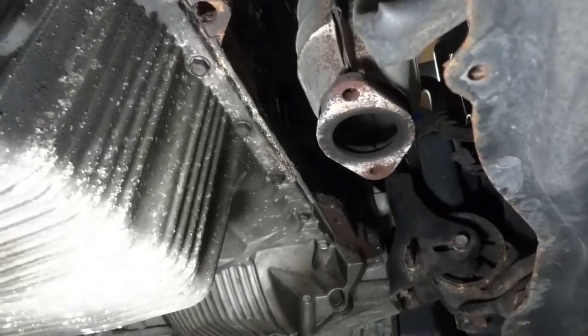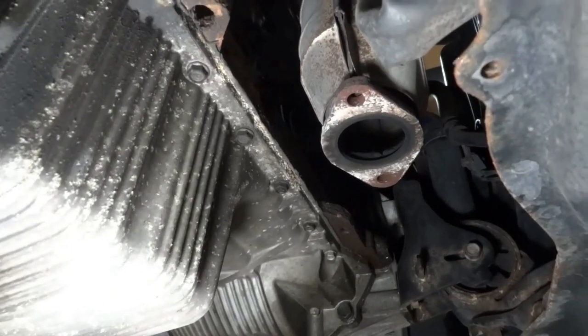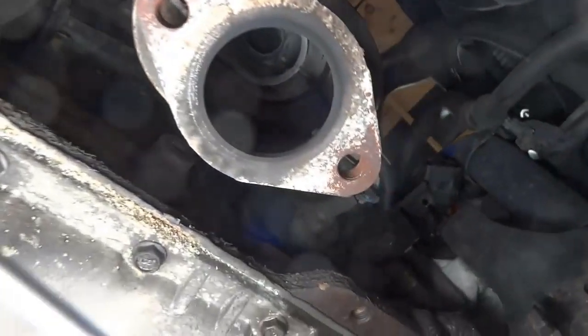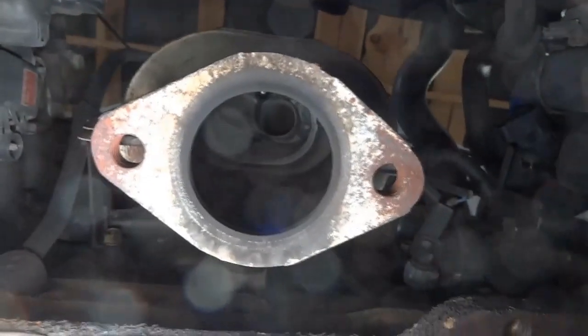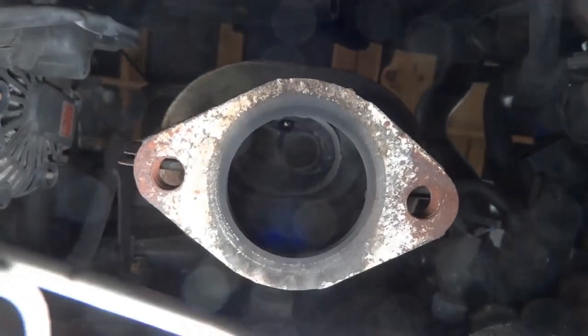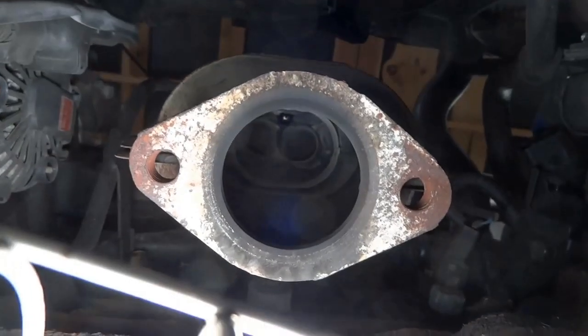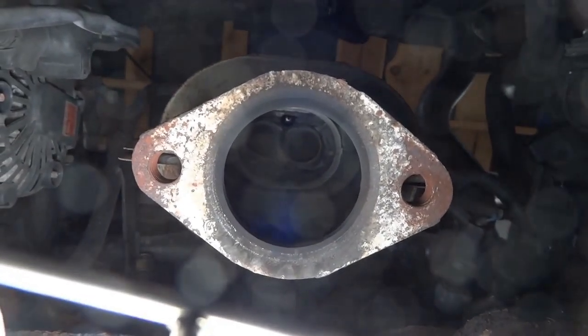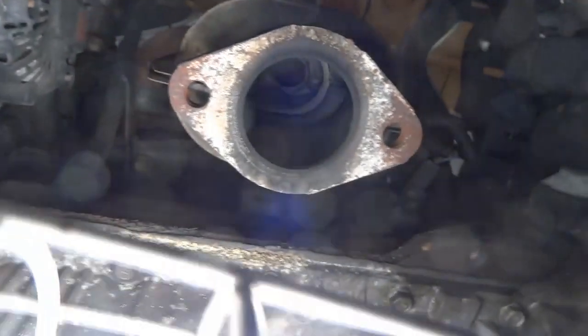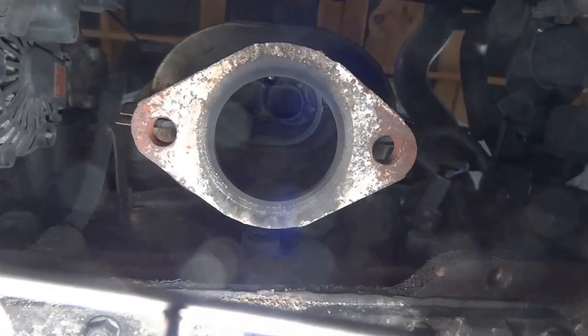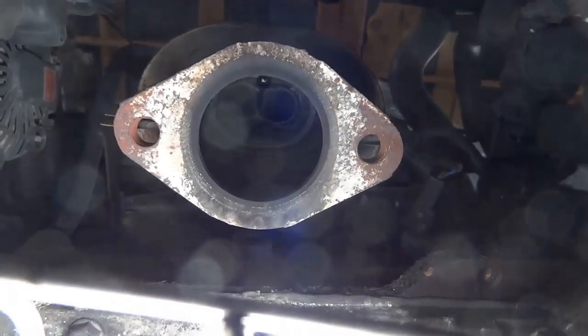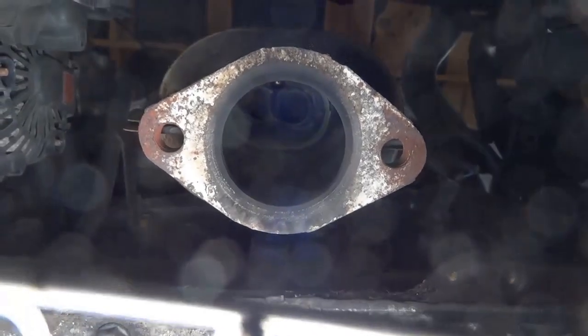Alright guys, so now we're gonna inspect the exhaust system. So let's check this catalytic converter first. So let's look in there. Wow, do you see that? That's not good. This catalytic converter is completely empty. There is no substrate in this catalytic converter. So where did the substrate go? This is not supposed to be empty like this. We're supposed to have substrate in this catalytic converter. So it's basically a hollow tube right now. There's nothing in the middle of this catalytic converter.